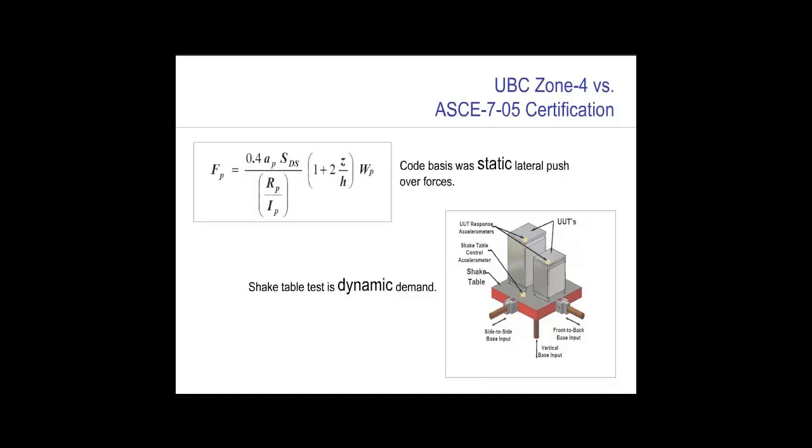Another reason this would no longer be valid is from an additional carryover from the outdated 1997 UBC, and that is of seismic zone maps. Usually one would have to be in seismic zone 3 or 4 before seismic qualified equipment certificates were required. However, as we reviewed earlier, the new IBC and CBC standards require that project-specific or site-specific seismic demand criteria be utilized. Let's see why.